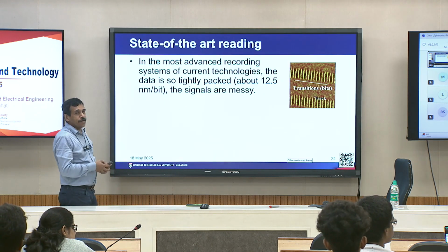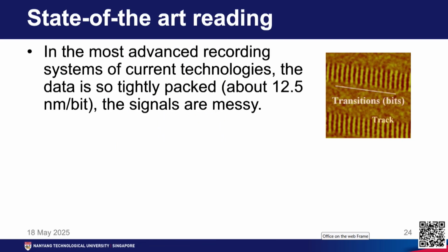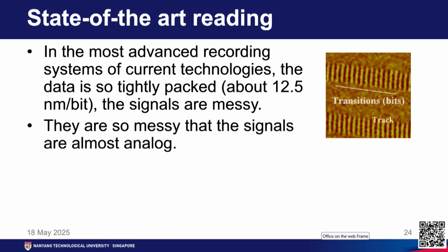However, in state of the art magnetic recording, I asked you a question, how long is one bit, right. Currently our bits are only 12.5 nanometer or smaller. Each line that you see here is so close to the next. I collected this picture using magnetic force microscopy, but in state of the art recording technology the bits are so close that I cannot take an MFM picture.